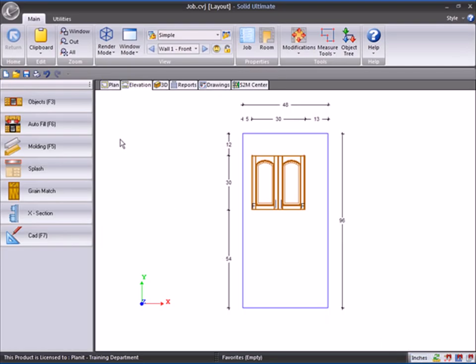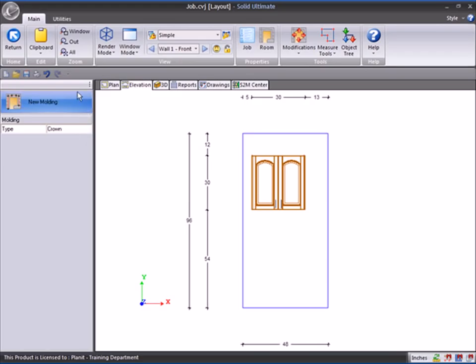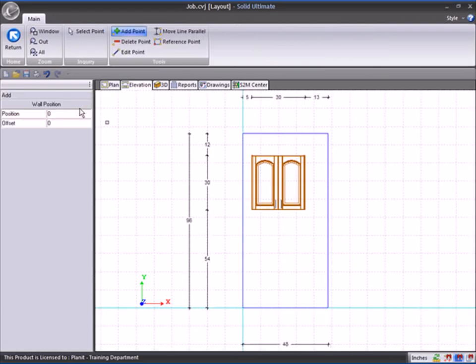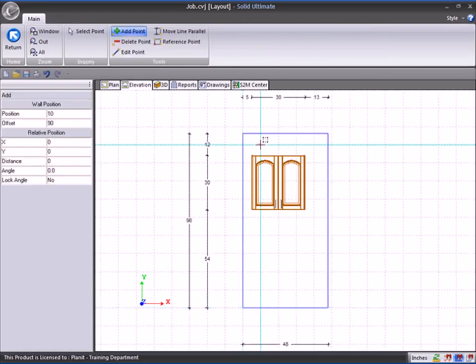Now let's go to the molding here, and I'm going to go down to the lower right and I'm going to click on the magnet with the grid on it. Notice the snap grid pop up. So I click there, the grid comes on. I'm going to draw some molding, and you'll notice that as I go to click the mouse, the icon on the cursor just to the upper right of the cursor changes. I can now place the molding and it will snap to the grid marks.